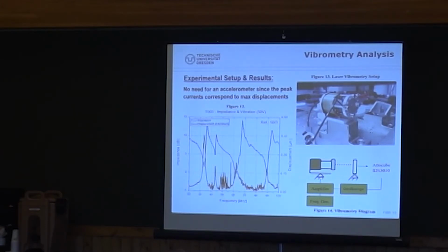I fixed the Woodward Thruster this way to a fixed bracket on an optical table, and then pointed the laser of the attocube directly on the aluminum mass, as close to the center as I could, and then saw the waveform, and did a Fourier analysis to obtain the maximal amplitude of the displacement. So that's the secret behind this diagram.